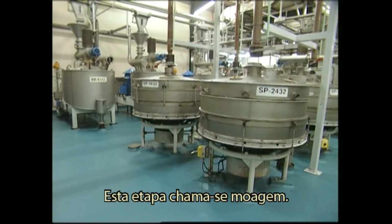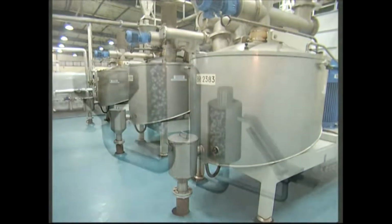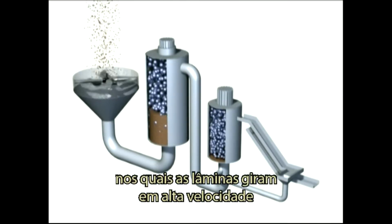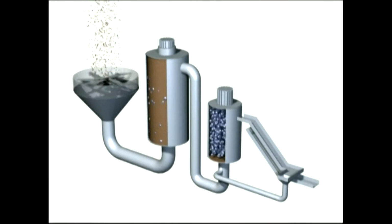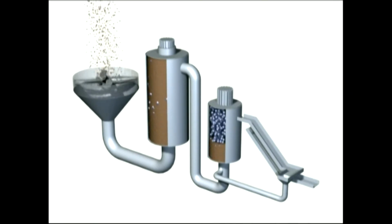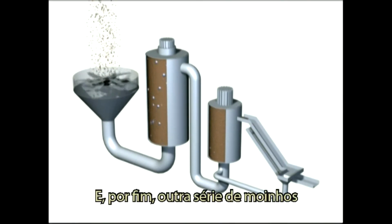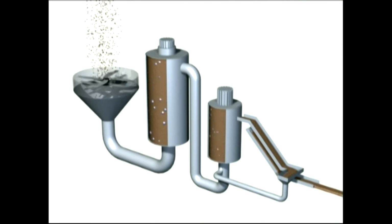This phase is called grinding. The nibs are ground in 3 steps to be transformed into cocoa liquor. The first step is the knife mills, where knives rotate at high speed and produce a coarse paste. Then, the ball mills, containing metal balls, refine it, and finally another set of mills containing metal spheres of a smaller diameter refine the liquor further.